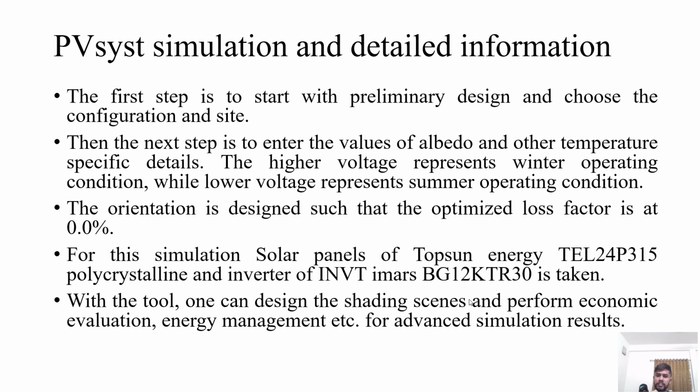These are design specific data that we have to feed in the software, and the other data which are dependent on the environmental conditions are directly fetched from the meteorological data available either from Meteonorm itself or the NASA website. The orientation is designed such that the optimized loss factor is at 0%.